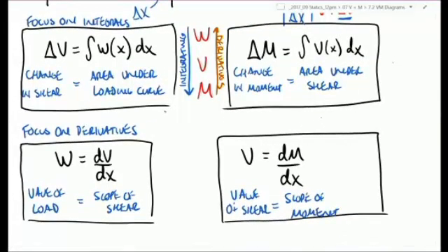But these are really the four fundamental rules that we'll use, because I'm going to teach this topic in a way that's really going to lean on these relationships. And then we can solve most of these problems kind of graphically. You can solve them really fast. You can look at them just like the areas under curves and slopes and draw your shear moment diagrams, sometimes without ever writing an equation. You can actually solve for not only the shape of the shear moment diagram, but also all of the values in the entire thing just by using these relationships right here.